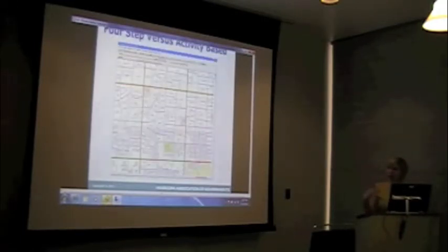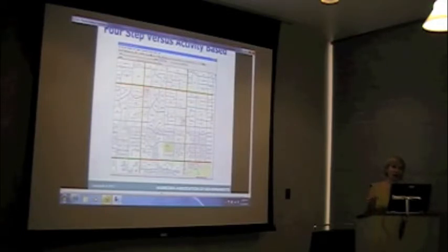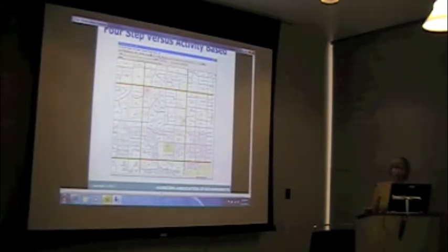All the data I'm talking about has to be available for every horizon year for which we want to model. So we have to have current data for the networks and the employment and the population, and we also need to have the same data set for future years. If we want to make a projection for 2030, then we have to have a network that includes all the projected freeways and projected future roads in there. And we have to have a projection for the employment and population.